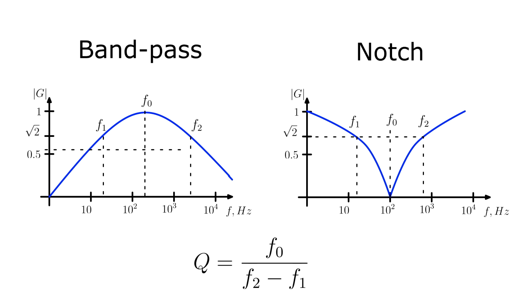The next twin pair of filters is the notch and bandpass filter. They are a combination of high-pass and low-pass filters. Notch filters reject only a specific part of the signal's frequencies, while its twin brother, the bandpass filter, passes a narrow part of the spectrum. These filters have two variants of parameters, either two -3 dB frequencies, low and high, or a center frequency f0 and quality factor, which represents the width of the filtered band. There is a relation that binds these parameters.